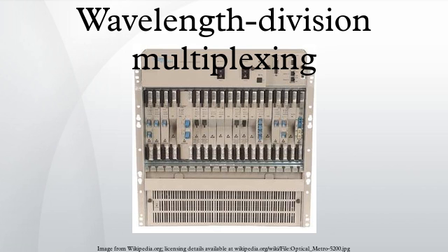At this stage, some details concerning wavelength-converting transponders should be discussed, as this will clarify the role played by current DWDM technology as an additional optical transport layer. It will also serve to outline the evolution of such systems over the last 10 or so years. As stated above, wavelength-converting transponders served originally to translate the transmit wavelength of a client layer signal into one of the DWDM system's internal wavelengths in the 1550 nm band.